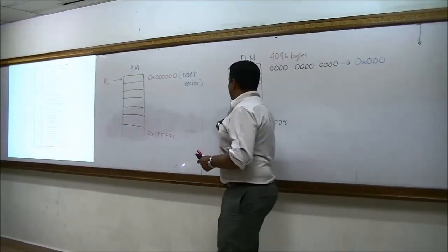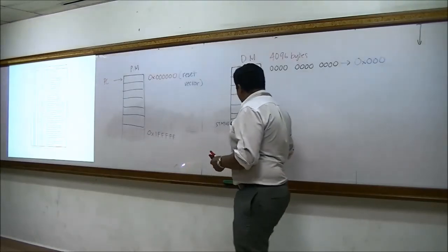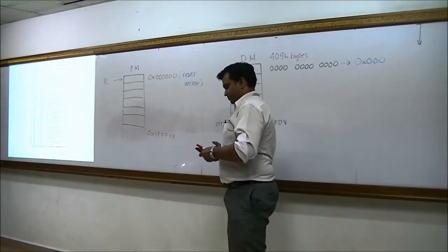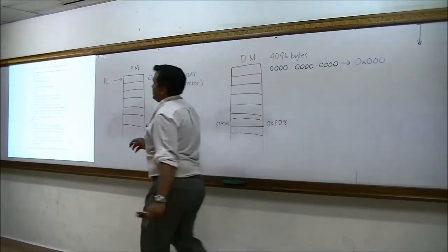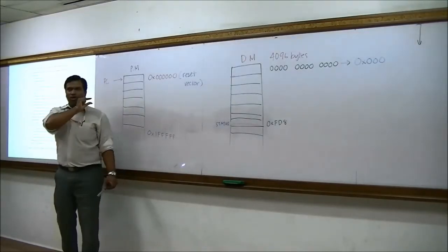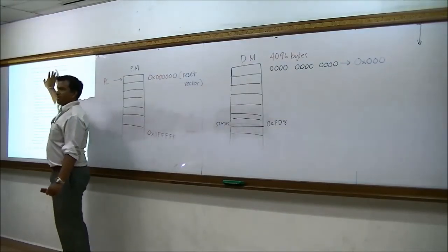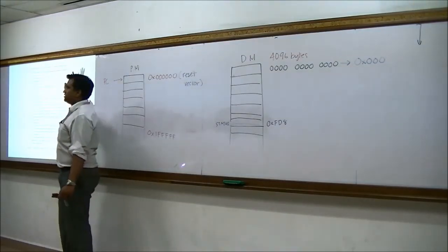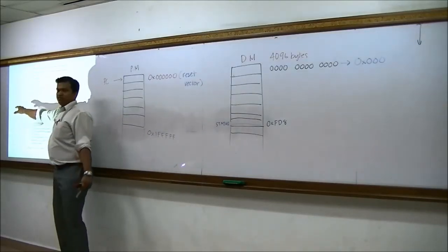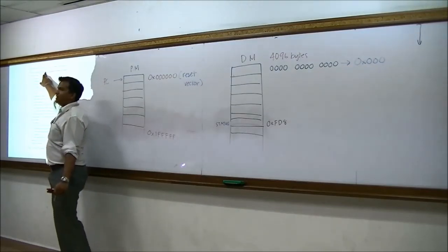So this is the status register. Now in one location, remember there are 8 bits, right? So that's what it's showing here. That's the 8 bits. So you understand where this came from? Just like taking the whole slot out and displaying it here. You understand? So one location can have 8 bits, but the status register is not using all the 8 bits. It's using only 5 out of 8 bits. So these bits are known as C, DC, Z, OV and N.